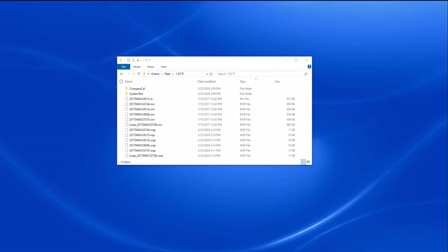For data collected using River Surveyor Live, it is necessary to open the data files in River Surveyor Live and create MATLAB files. SonTek has not publicized the data format for their raw data files, and thus MATLAB files created by River Surveyor Live are the only SonTek files that QRevInt can read. QRevInt can read the system test and compass calibration files, but those folders and associated files must be in the compass cal and system test subfolders for the measurement as shown here.